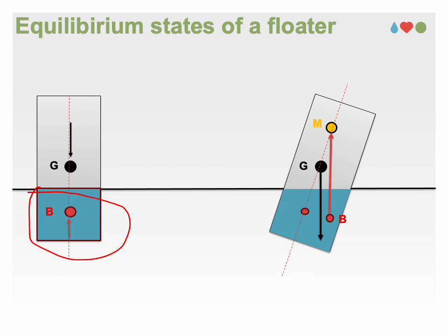Now, if the cylinder is slightly tilted clockwise, the buoyant force acts to restore it to its original position in counterclockwise direction. Note that the center of buoyancy moves towards the right from its origin, in this case, because there is more bulk of displaced water or volume here.